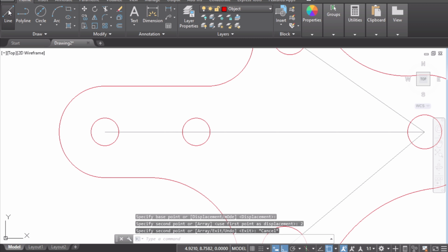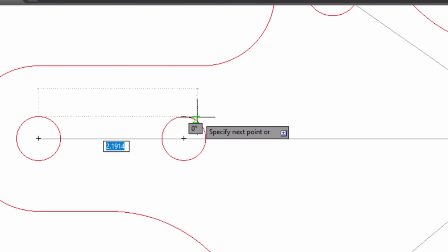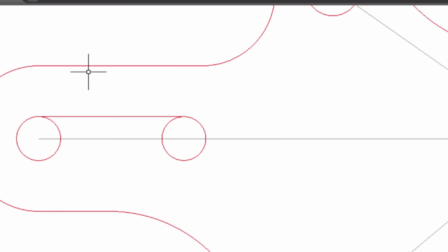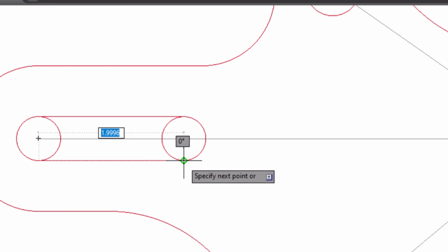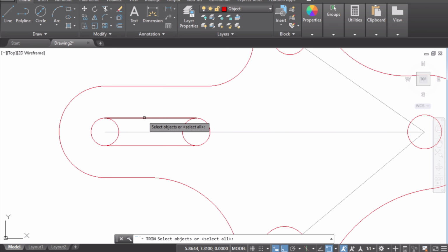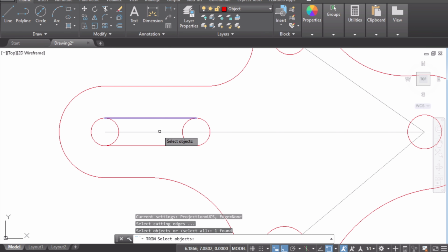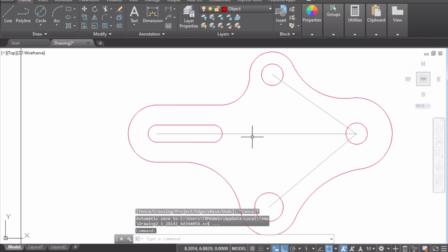Now it's easy, choose the line and connect the quadrants. So this is the quadrant point, select here and fix with another quadrant point and choose the line, select this quadrant point and this quadrant point. Make sure ortho mode is on, click. That's it. Now we have to trim out the inner portion. I need the trimming tool, select. I need the connection between this line and this line, then enter. Now you can trim out the inner portions. That's it. We managed to make that slot.